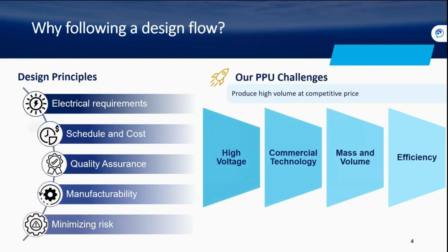For example, the high voltage requirements are super demanding in both projects, and this means added complexity. For instance, our positive high voltage module has to provide up to 1.5 kilovolts to the thruster screen grid. As you can imagine, when designing, this means adding a lot of restrictions, for example with PCBs, testing assemblies, or validating components. So yes, this is quite a restrictive requirement.